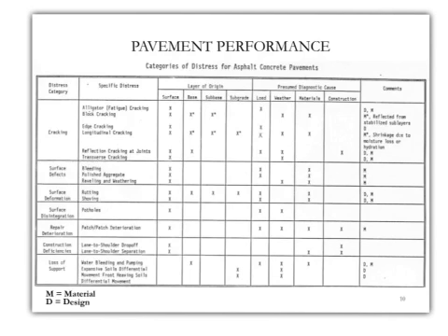It's going to let the water in, and this is where we see the disintegration between aggregate and the asphalt, all the way to the loss of support. Again, if we pick on the expansive soils, it's mainly because of weather. The water is going to get into the system, it's going to make its own way to the soil. Once we get to the soil, it's going to expand and it's going to make the entire structure fail.